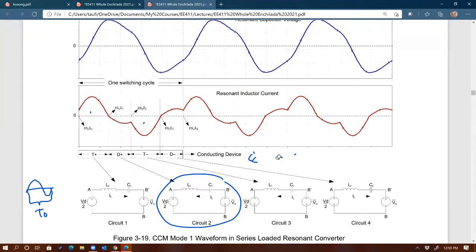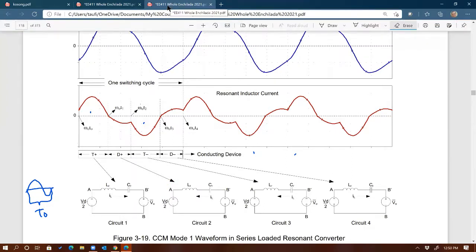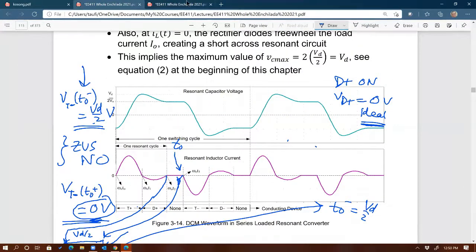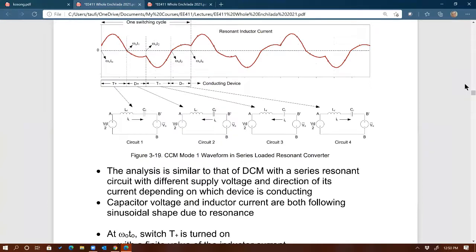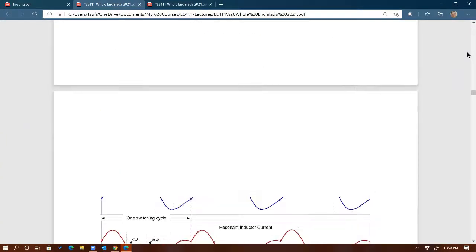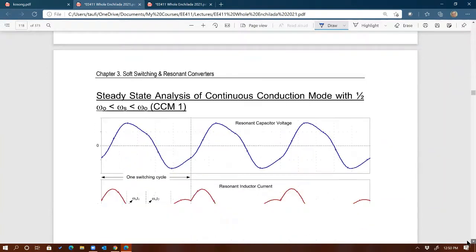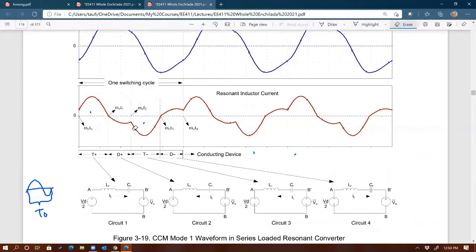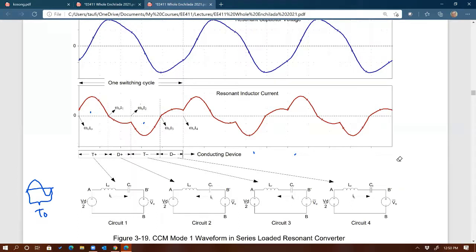All right, so let's do the table again quickly. I'm just going to do it one more time, and then we'll move on to the next topic. Let me go to the next CCM. Is it this one? It is this one. Okay. First of all, before we do the ZCS and ZVS, looking at this waveform, can I use a thyristor for this one? A semi-controllable switch.